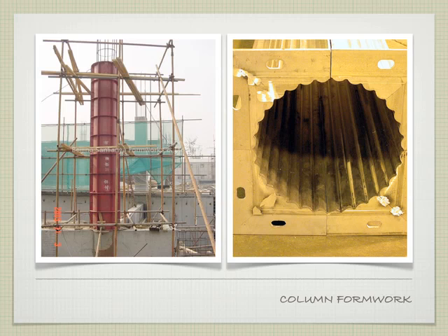Notice, however, if you have these flutes, we couldn't have this be half and half. We need this to be broken into quarters because you need to be able to remove the quarter. So if, for example, this was half, and we had these little pieces, that would lock the formwork into place. So it needs to be split here and here so we can actually remove this corner after the concrete's been poured.